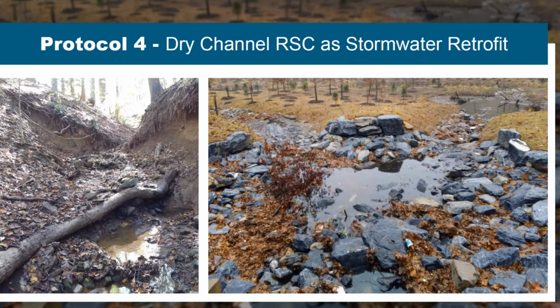Protocol 4 is really just about cleaning up your outfalls as part of stream restoration projects. This is almost becoming a standalone practice, but typically when you're doing stream restoration it's a great chance to connect the outfalls across the floodplain, maybe get rid of some point discharges, create a little overland flow, or get rid of a lot of these.